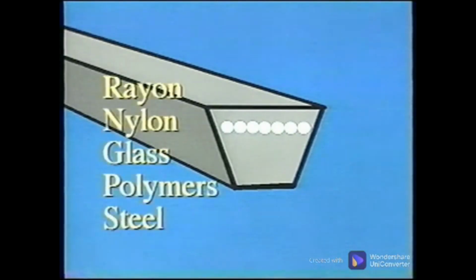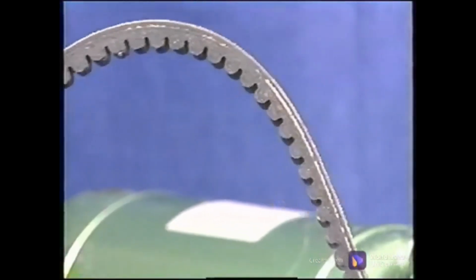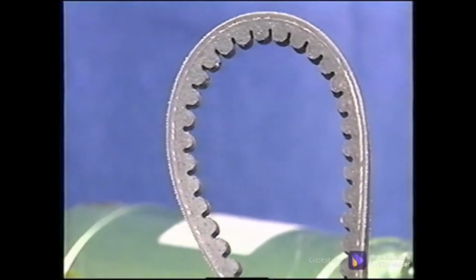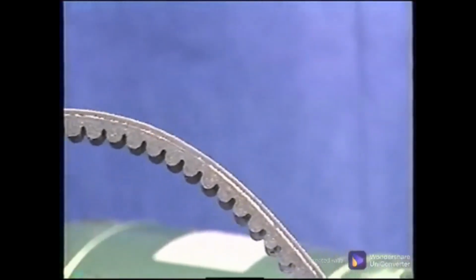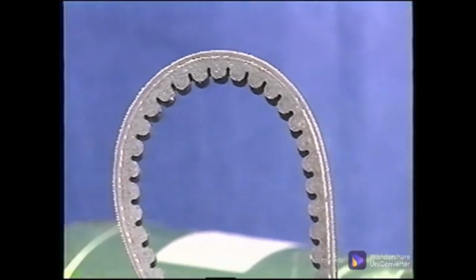Depending on the load to be carried, the cords can be rayon, nylon, glass, polymers, or even steel. There can be one row of cords or several. These cords are encased in a harder rubber for strength and to keep the cords from migrating to other regions of the belt. A variation of the standard V-belt is a cog belt, which allows more flexibility in the compression section of the belt, allowing it to be used on smaller diameter sheaves.